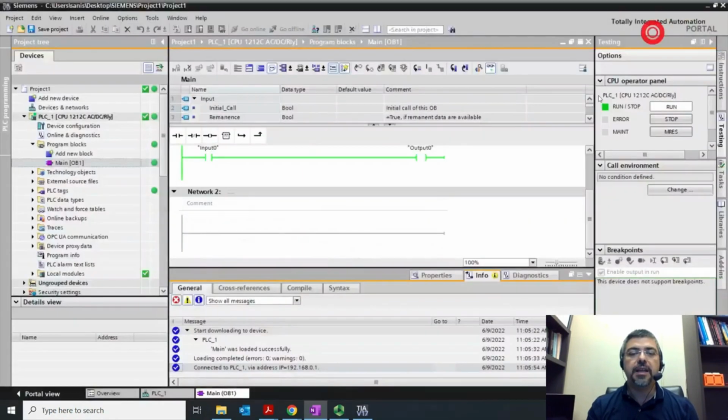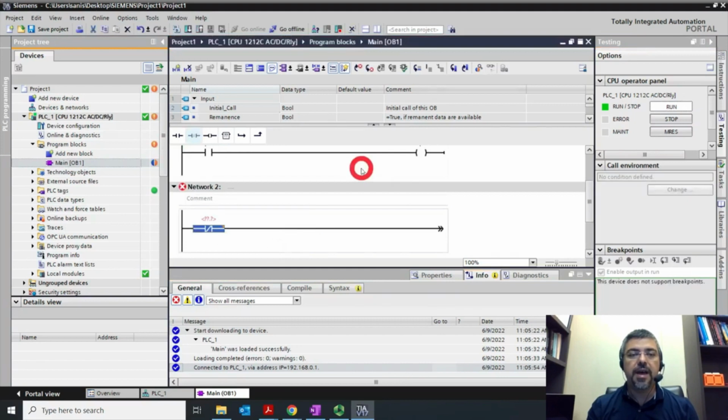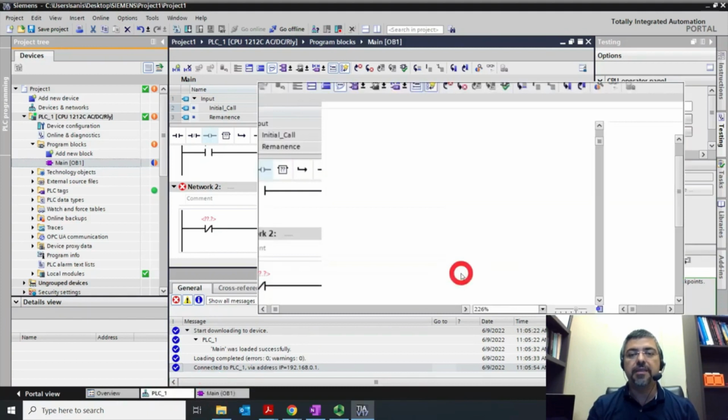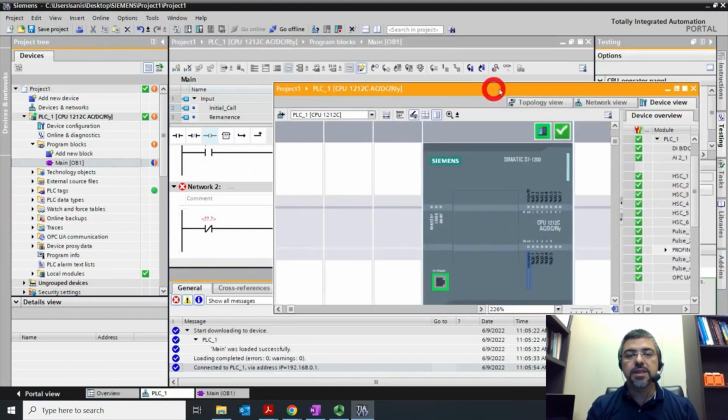So back here and implement the same thing. So easy. I just drag and drop this normally closed one here. So I have it. Then I come here. I need one coil. I put that here. Similar to what we did, we come to the PLC here, and you tell me what we should set up there.